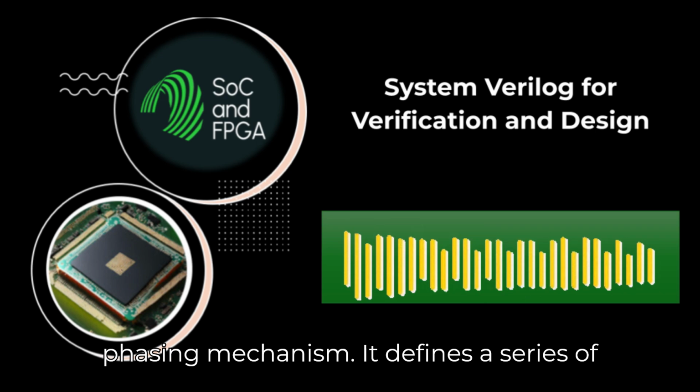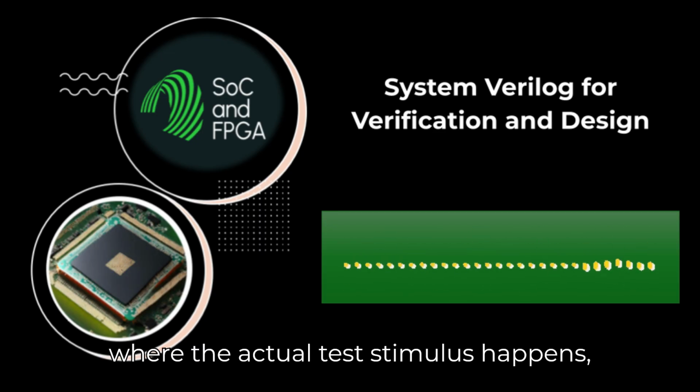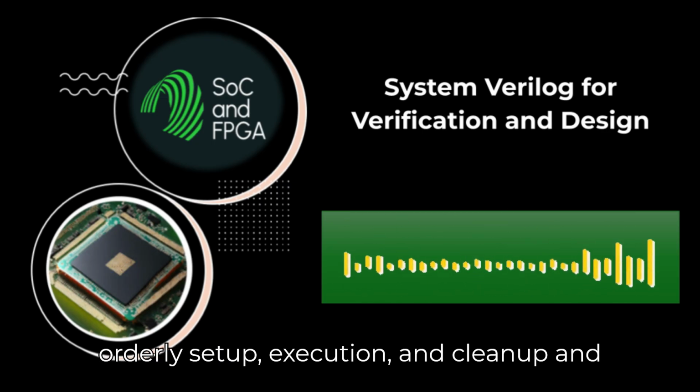It defines a series of standard phases, like the build phase where components are created, the connect phase where they're hooked together, the run phase where the actual test stimulus happens, and the report phase for results. All components execute these phases in sync, ensuring orderly setup, execution, and cleanup.